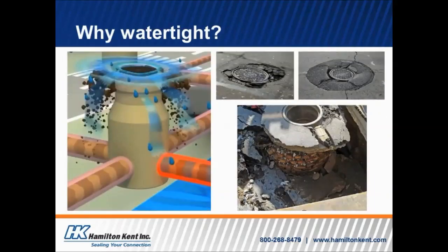So why watertight? Quite simply, as water goes into the ground, between pavement, around a manhole frame, however it gets into the ground underneath and around a manhole, if there's a place for water to flow into a manhole or pipeline, the fines in that soil are going to slowly be pulled into that pipeline. I say slowly, but it could be quickly as well, depending on how big that opening is. But over time, this erosion of the soil can cause the pavement to crack and sink, resulting in consistent repair problems and possibly large failures.